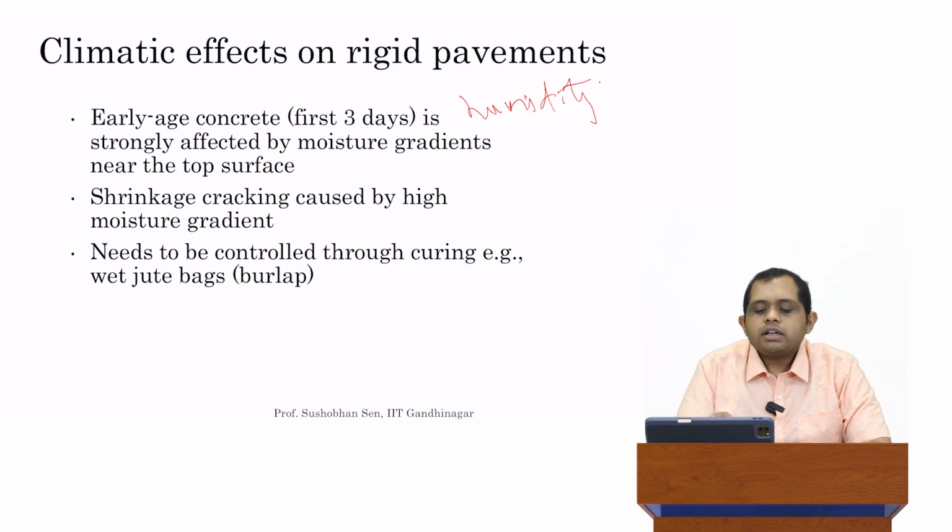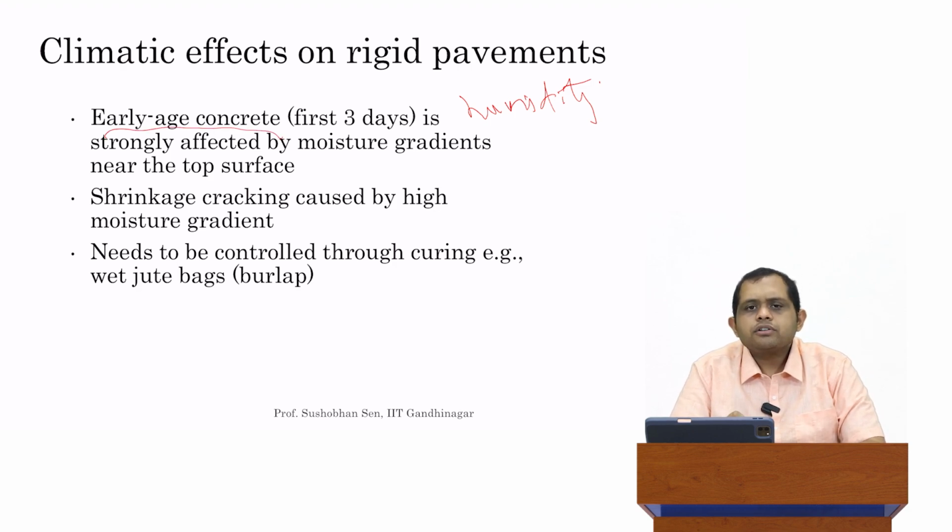Why? Let's consider early age concrete. I've assumed all of you have taken a class on concrete, so you probably know that concrete is basically cement, aggregates, and water. When you first mix them together, it's a fluid-like substance. It's not water, but it's some type of fluid which flows and has a flow rate. So basically the shear stress depends on the strain rate. That's what we call early age concrete.